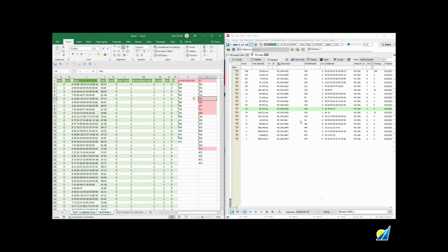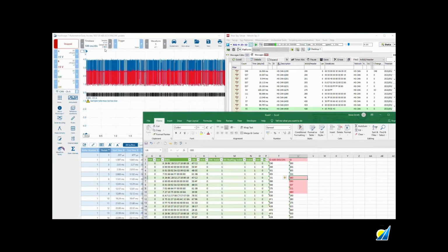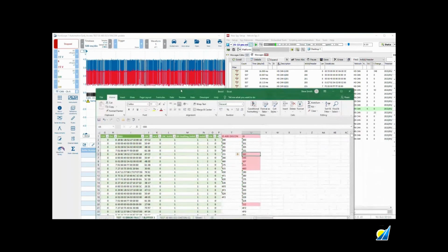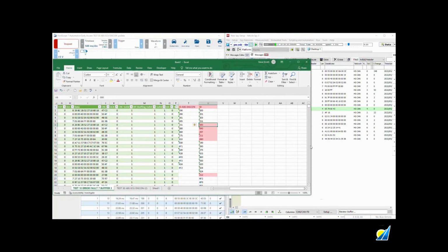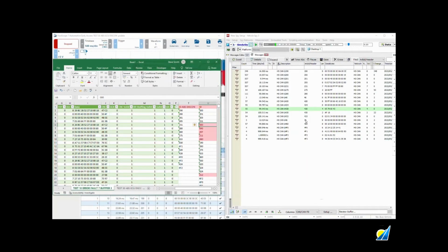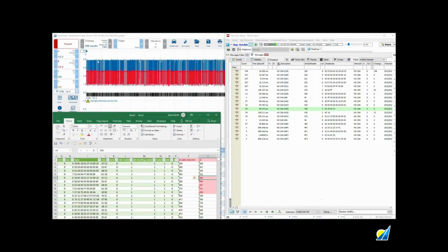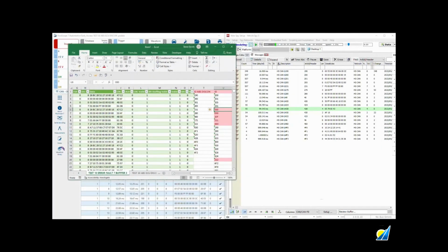So I just want you to be careful that when we used PicoScope, we did a sweep at 500 millisecond divisions. But these IDs here appeared to be transmitted at a very slow poll rate. And it could be that in a sweep, where you looked at CAN traffic with your ABS ECU disconnected, these weren't present simply because they weren't transmitted during that time span. So with Vehicle Spy, we were able to leave it running for a long time, seamless logging. Alright, I hope that helps.